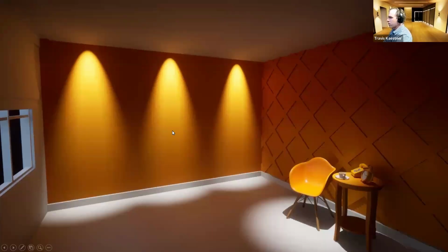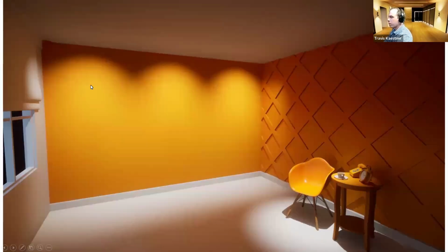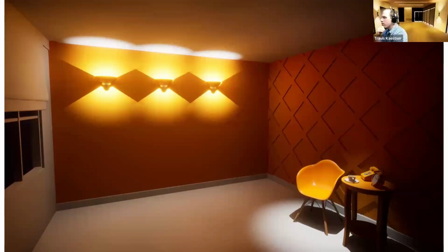Just some other options, you do some light and shadow. That's kind of popular. You can expand your dual recessed downlight wall wash. Stagger them and space them equally. There's a whole calculation. You look at the wall wash fixture itself, and you can create an evenly illuminated wall with just a few downlights if that's what you want to do. Wall sconces do kind of the same thing, indirect uplight, downlight, and light and shadow. I like groups of 3. I like odd numbers. Sometimes that's not always the best.